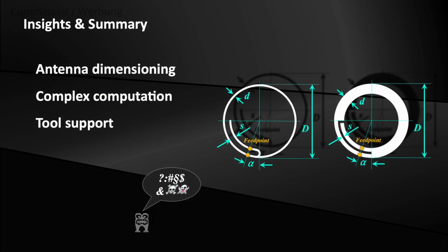The insights. High frequency engineering can get complicated. This is particularly the case when one wants to exploit resonances. Then certain current and voltage levels are distributed along the conductor, and it is not easy to calculate what effect the connection has at a certain point. However, with the small Excel tool, you can now calculate a lambda loop antenna, including the associated matching network for any frequency. This is always a good start if you want to make such an antenna.